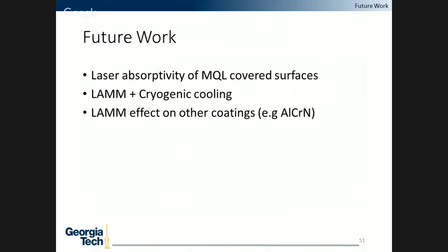And from our results, some areas where research could be continued are, as we said before, we did hypothesize that MQL oil led to increased absorptivity, which also suggests that oil does increase absorptivity in near-infrared lasers, as shown in the literature. Yet this needs to be further experimented or modeled by studying the laser absorptivity of minimum quantity lubrication oils under laser.